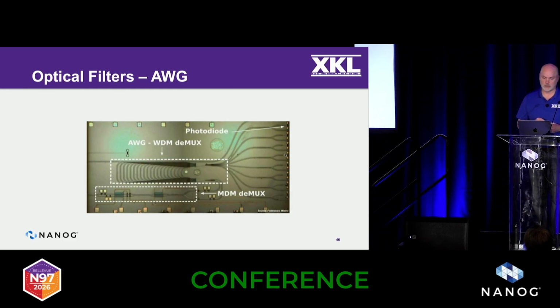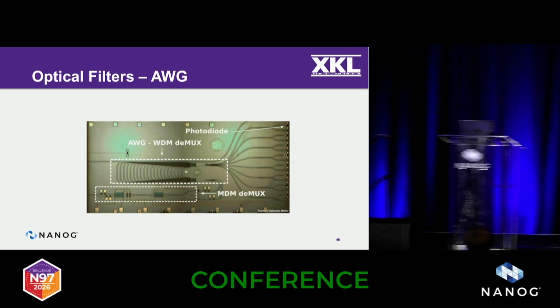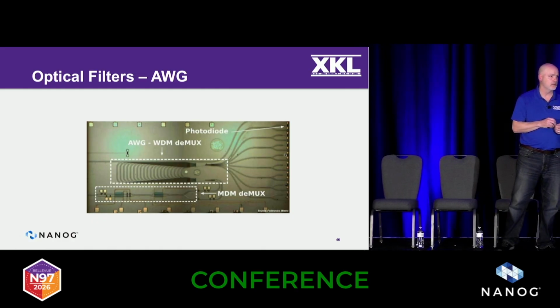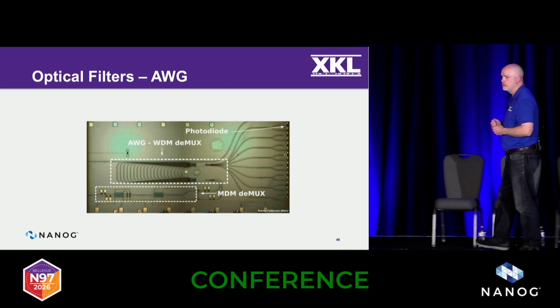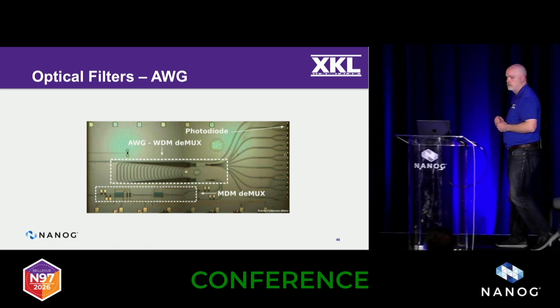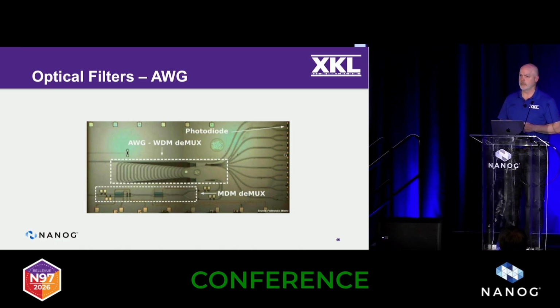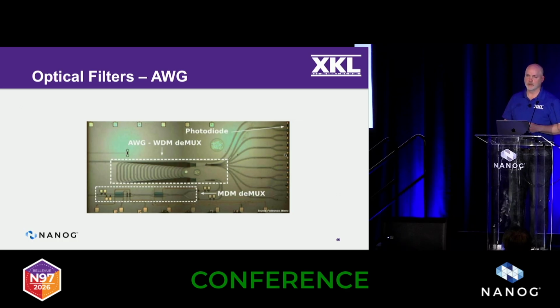This is an X-ray of the chip. There's your waveguide, and you can see the bunch of channels and different length paths that the light has to take. This is a really good example of how this works. It's a chip. It's manufactured. It's not a bunch of fibers, not layers of film like the thin film. And this is why it's so commonly used for many, many channels. It's got a lot higher insertion loss, but it can accommodate 96 channels.